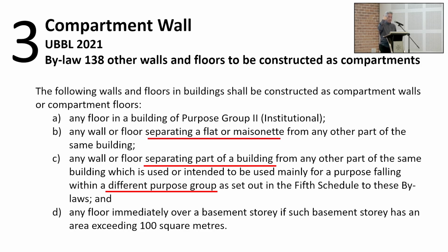Okay, so first, the overriding definition for compartmentation is that you have to compartment things to keep all fire compartments within the prescribed limits in the fifth schedule. Then on top of that, for flats, individual residential units in a complex, every one of them must be compartmented irrespective of volume.